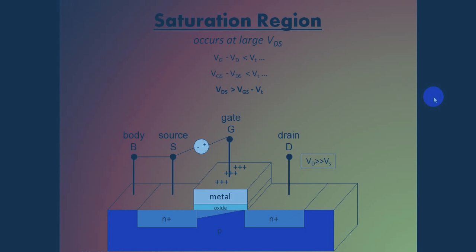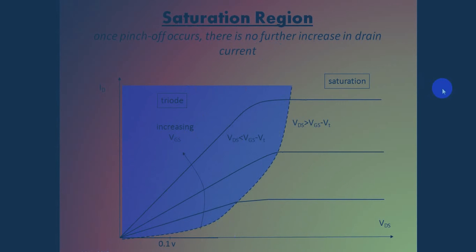However, since the drain voltage is higher in this case than the gate voltage, a part of the channel turns off, and this mode corresponds to the region which is also known as the pinch-off voltage. Therefore, we see that there exists a voltage in between the linear and the saturation region that is discussed afterwards. Coming to the saturation region curve, here you can see the triode region is given, and this is the saturation region that is present.